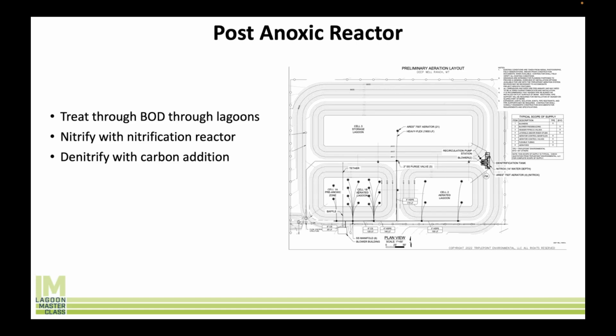That is raising the DO, that's fostering the growth of nitrifying bacteria, which is then nitrifying, right? Converting the ammonia that came in into the nitrate that we need to denitrify. And then we're running it through a denitrification reactor directly after, where we're seeking to foster the growth of denitrifying bacteria in order to get rid of the nitrate and turn it into nitrogen gas.